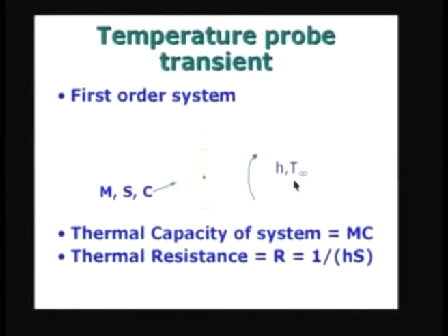The second case is where the temperature T infinity is actually varying with respect to time in a linear fashion, which is normally what happens if you start heating, for example, an oven which is in the off position. You turn it on, initially the heat is input to the system and the temperature is likely to vary in a linear fashion. Or you may set up an experiment where you want to specifically heat an object at a constant rate of temperature increase with respect to time. So, then I would like to follow the temperature as it changes for that particular experimental purpose.